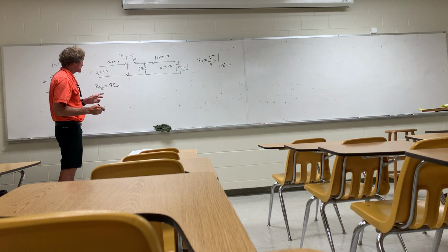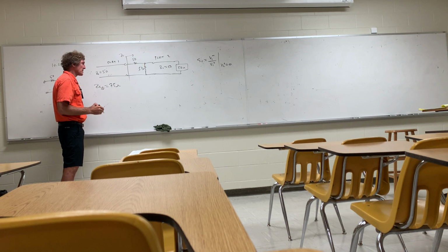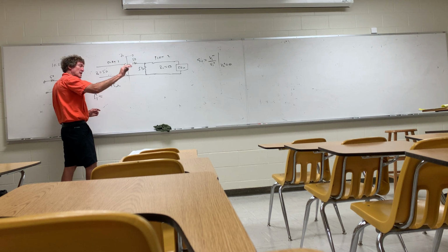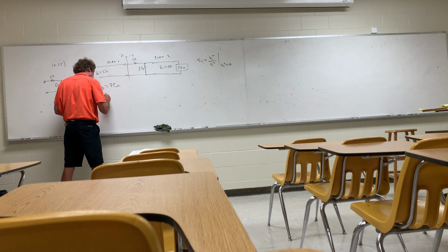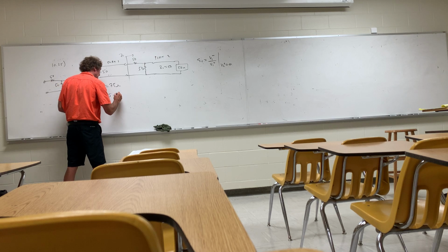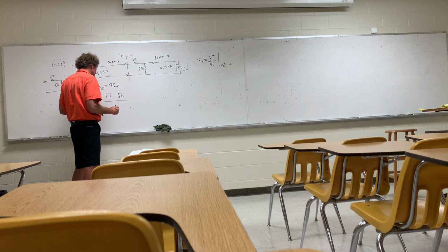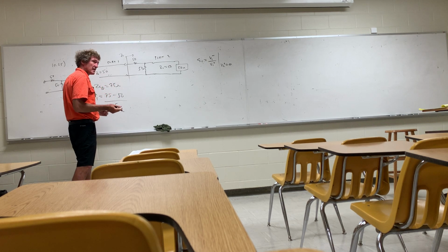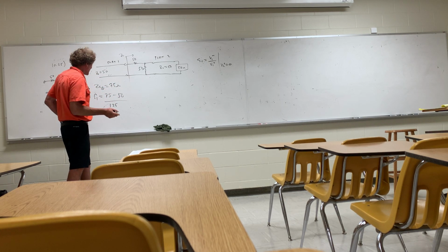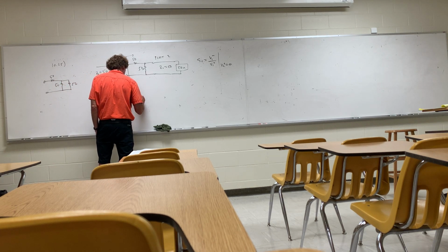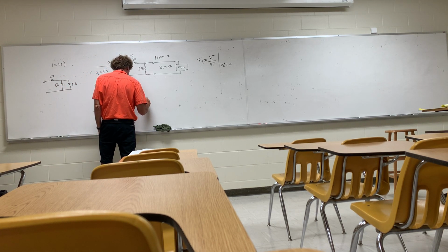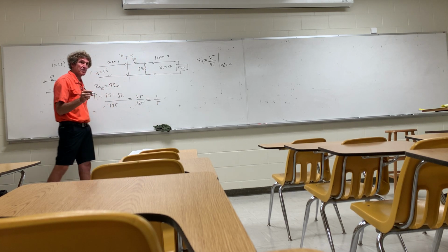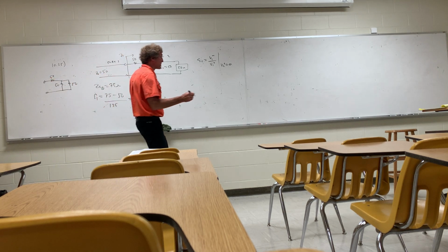So when I look at this, the input impedance there is 75, which means the reflection coefficient at port 1 would be what? The impedance I go into, 75, minus the impedance I came from, 50, over the sum of the two, which is going to be what? 125, is that right? Correct, class? And what's that going to be? Well, that's 25 over 125, right? Or it's 1/5. You all agree? So that would be S11, 1/5.